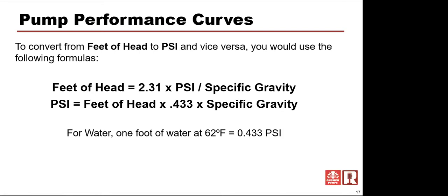We were talking before about different types of fluids and being able to convert from feet of head to PSI. These are your formulas for that. When you have reference in feet of head, if you knew what PSI you wanted, say 40 PSI, you would take that times 2.31 to get to the number of feet of head. Well, what is that telling you?